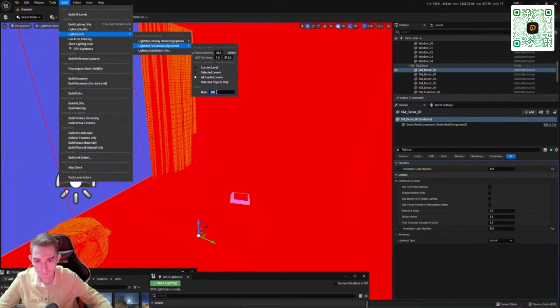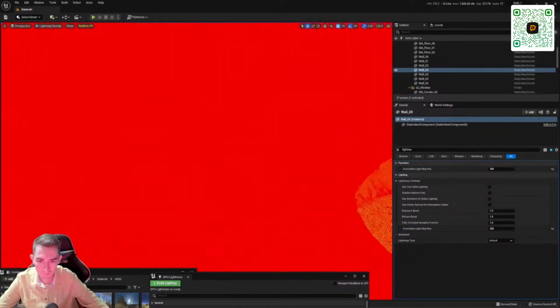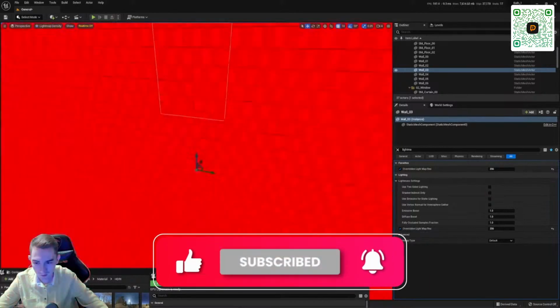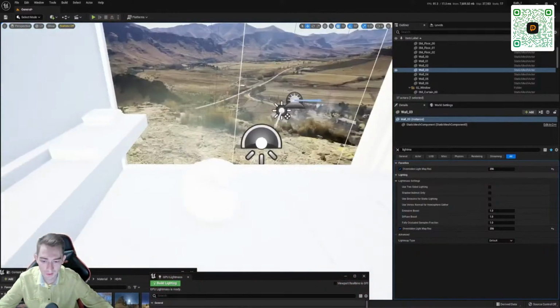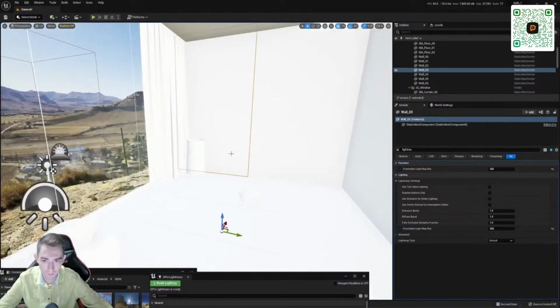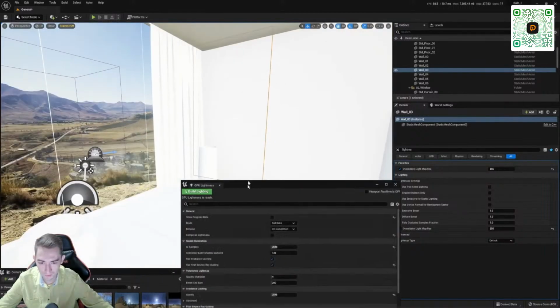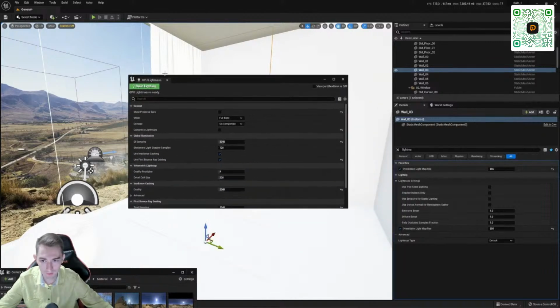Now I'll set 100 and that's it. So now we have everywhere, if we look, a high-quality light map resolution. So, I switched to lit mode, and we see that our baking has gone wrong. When setting up the light map resolution, the baking is lost. This is normal. We're not doing anything about it. So, here we do not forget to turn off the real-time viewport so that we do not lag when baking. And click on build lighting.